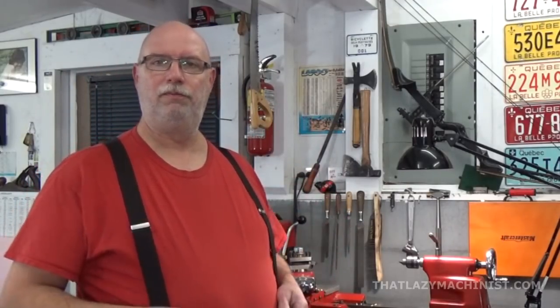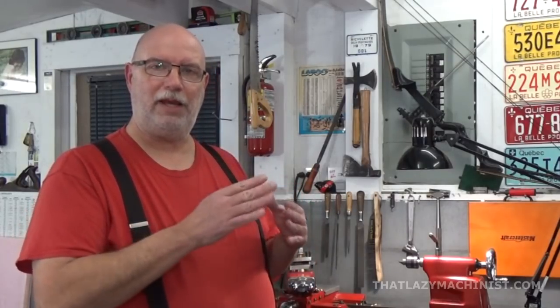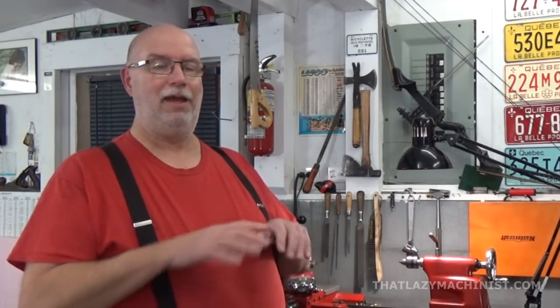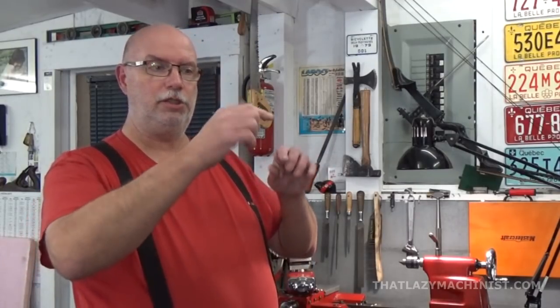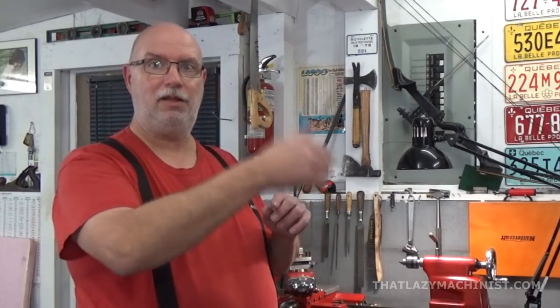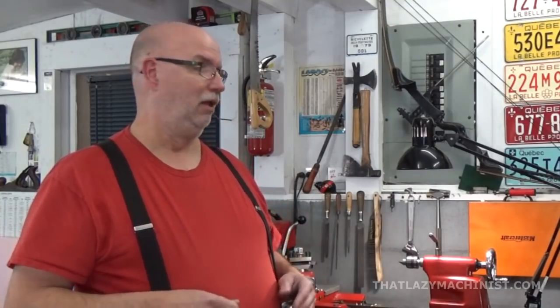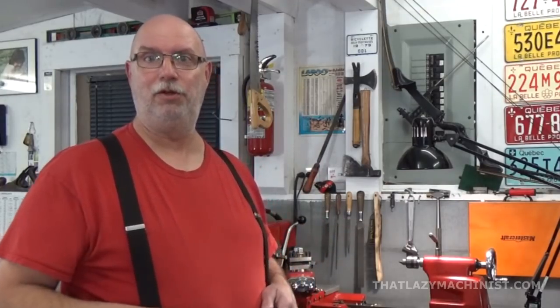So what can you do? Well, you don't have to create a full surface. If you take your first pass to set up your 0 on a part that you know measures the right diameter and it's a little offset, if you take successive cuts until you touch just half of the diameter of the part, just half machine, not the other half, well, that means that where the two halves meet on each side, that is exactly 1/2 inch, and that's your 0 to start out with. So if I touch off here and I realize that I do have a little eccentricity, that's what I'm going to do.